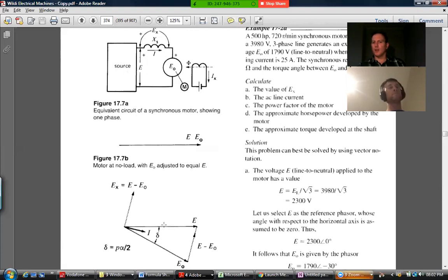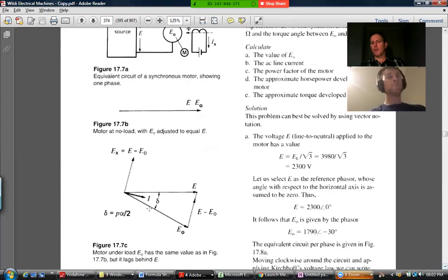So you don't see it, but bear that in mind, because if you just look at this, you'll think to yourself, hang on a minute, I'm seeing current to the right, I'm seeing the voltage vector to the right, regardless of whether this current is slightly below this line, as it is for a motor, or slightly above that line. If I do I times E times cos of that power factor, it would look like you're going to get a positive number.